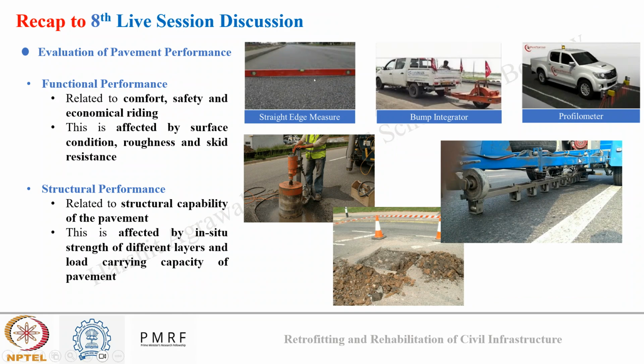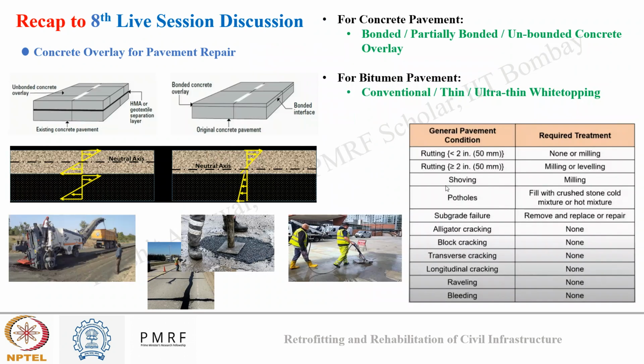We saw how at one point the load is applied, and using different geophone sensors, we record the deflection away from the load, and from the profile of obtained deflection versus time, how we can back calculate the performance of a pavement. Now, after quantifying the performance, there comes repair, for which we discussed concrete overlay as a repair strategy.